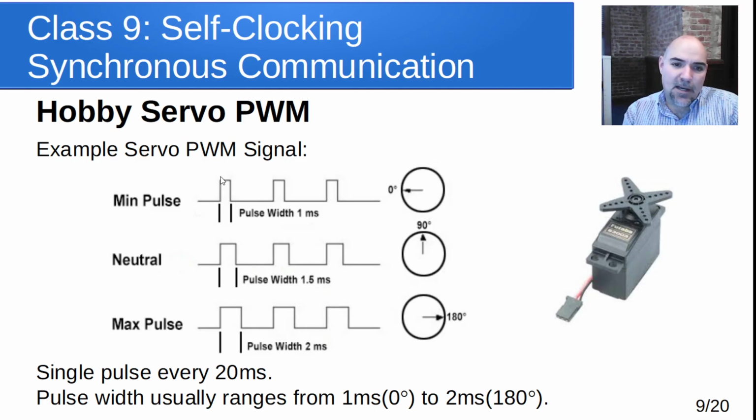Set the pin high, have a delay for a certain number of microseconds, and then set the pin low again. And if you hook that up to a servo, the servo control line, which is usually white, sometimes yellow, depending on the servo manufacturer, you give this thing power and ground and the control signal, which is white, and output that from the Arduino, and you can now control that servo from one of the port pins on the Arduino.